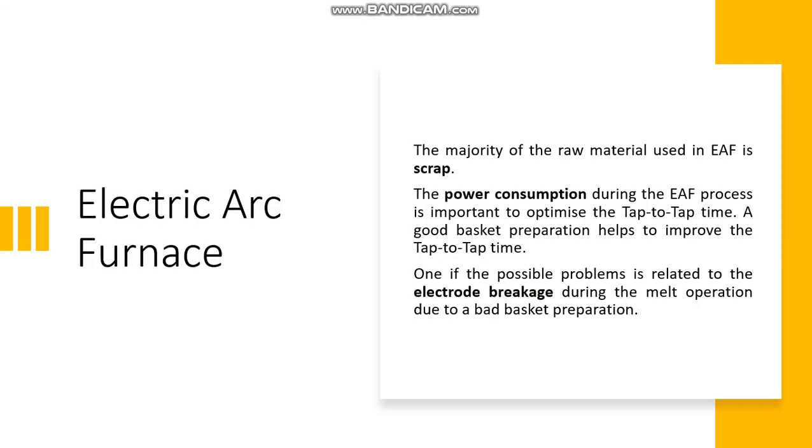The majority of the raw material used in EAF is scrap. It should be selected to obtain the best condition to prepare the basket, to avoid possible problems in the operating condition. The power consumption during the EAF process is important to optimize the tap-to-tap time. A good basket preparation helps to improve the tap-to-tap time.